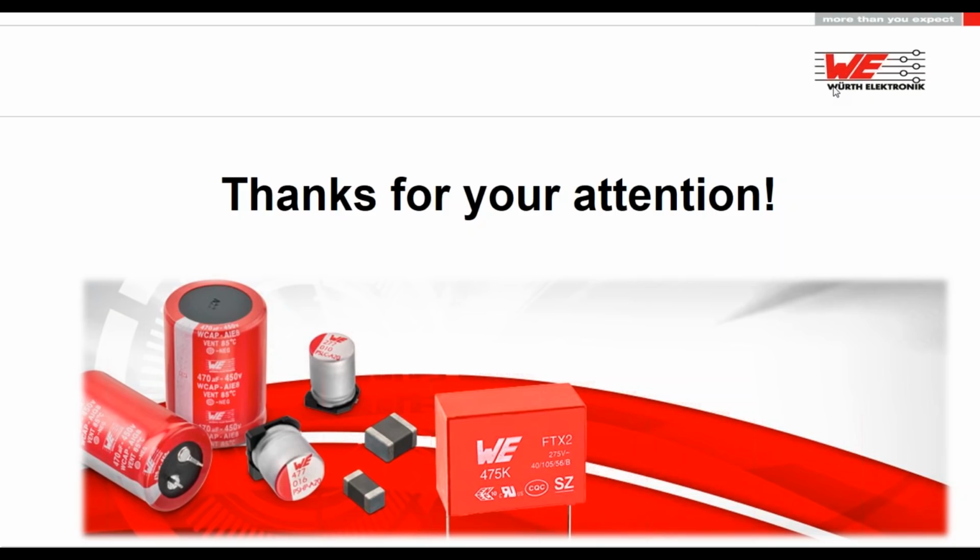I know, sure, if you go for high cap values, you have a strong issue, because if you get in the range of 100 microfarad, you do not get any rated voltage of 16 or 25. But what to do then? Go back to smaller cap values like 47 or 22 and take a few of them, because then you get a higher rated voltage, and a few of them can still be cheaper than one 100 microfarad. And sometimes it's better to take 2 times 47 microfarad with 10 volt instead of a 100 microfarad 6.3 volt, because the capacitance yield will be way, way better. So with 2 caps, you still get way more capacitance.